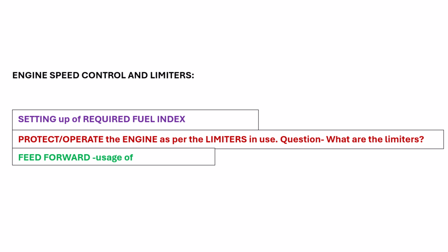But when a large amount of steam starts to flow, let's say three turbines are started one after another, a lot of steam will be produced. We call it ebullition. So the virtual level of the water in the boiler will actually be more. But the steam going through the steam stop valve will carry some water up also. So in fact, it will look as if the water level is much higher.